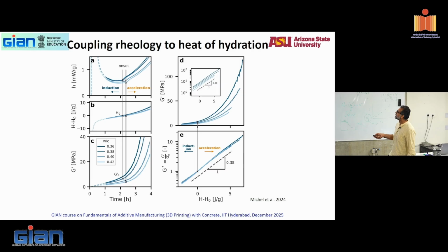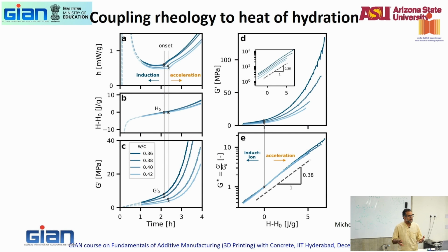So if you look at doing it, here is your induction period, right? Nothing is happening. And this is all dissolution. So we really don't bother too much about dissolution. That's anyway happening. Acceleration is where you actually start to produce your hydration products, and your initial set is somewhere at the early part of your acceleration curve in your hydration curve, if you know that. So that's your heat release, that's my cumulative heat.